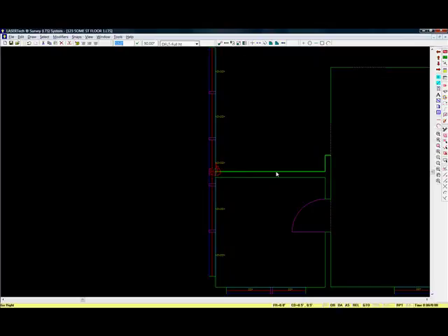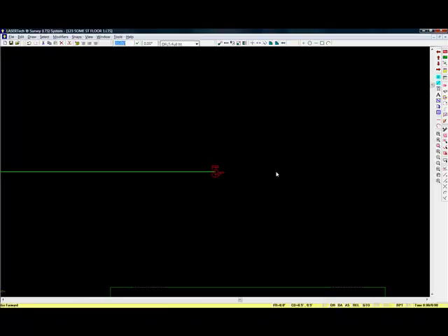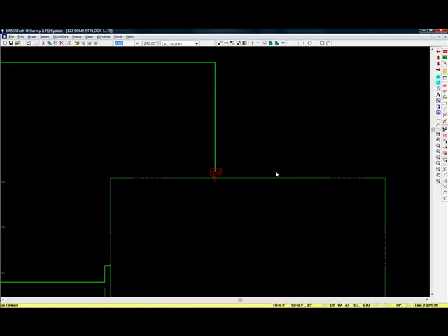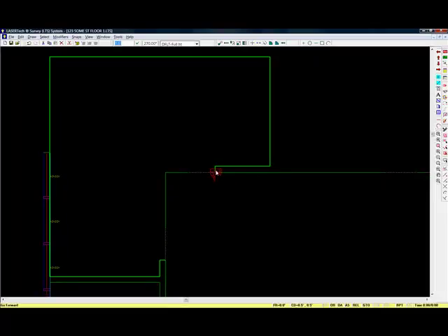Now we turn here and we go 20 feet, and we turn again and we go 20.05, and we turn again and we go 9.95, and we turn here and we go 5 feet, and then we're going to turn and close and adjust this chain. As soon as we go past a door opening where we already have a point located, we want to close and adjust any error to that point. So we do our closure check.